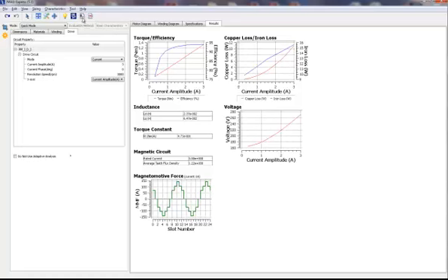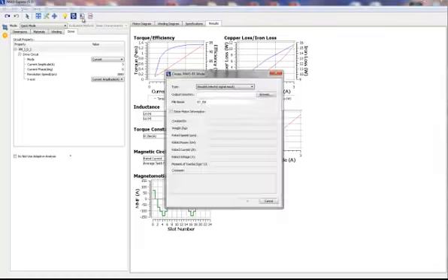If we wanted to do an RT-based analysis, or create that RT model block, we would select that button, and then we would select the output directory and the type of RT block that we want to create: a Simulink electric signal block, current signal input, voltage signal input, PSIM block, or something for LabVIEW, for instance, for the National Instruments hardware-in-the-loop simulations.